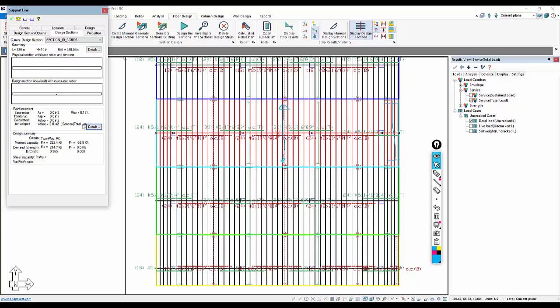If we do a calculation and we take 336 times 10 and multiply that by the required temperature shrinkage, 0.0018, we get 6 square inches of steel. And that results in so many bars.